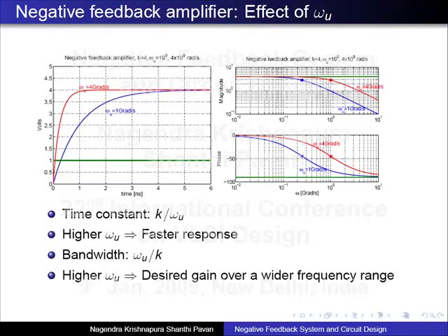Okay. Anything else? Yeah. I think we should call it a low pass filter only because the integrator, when it acts as an integrator, the phase shift is 90 degrees. That's right. So the integrator itself has a phase shift of 90 degrees. When you enclose the integrator in a feedback loop, the net system has a different phase shift.